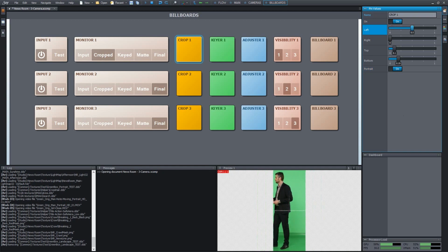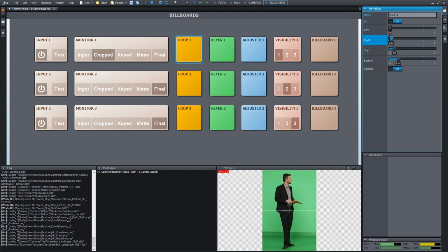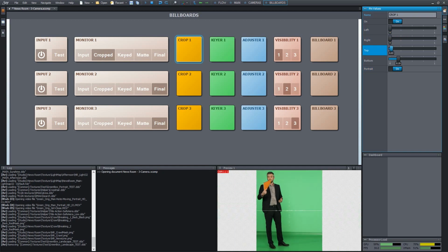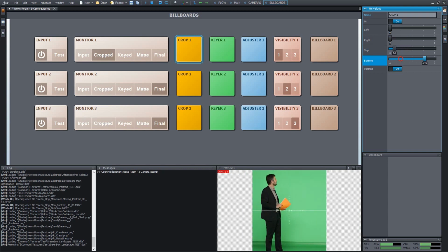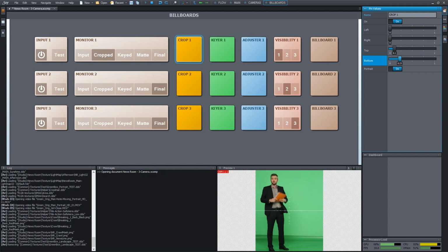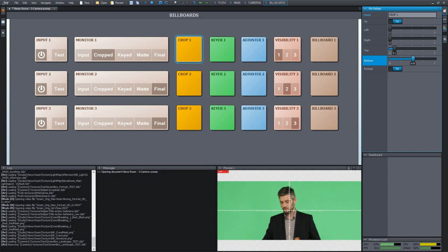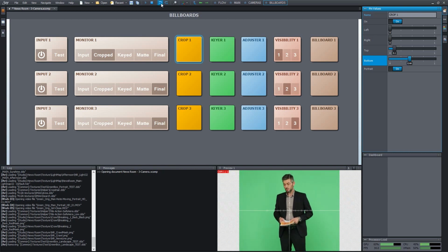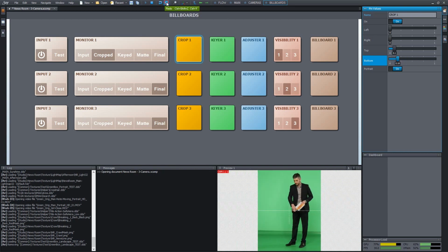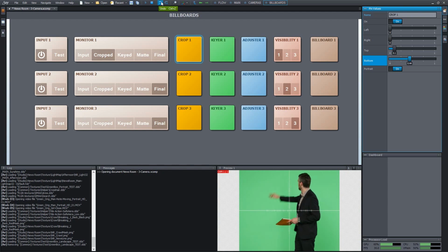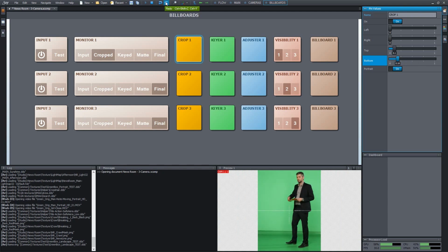The crop action of the 4 sides of the rectangular image is done by these 4 sliders. In the case that we need a fine adjustment, we have to keep the Shift key pressed down while moving the sliders horizontally. As we see, this will result in a much slower adjustment on the image. During these actions, the standard undo, redo functions and their corresponding Ctrl-Z and Ctrl-Y keyboard combinations are always applicable.